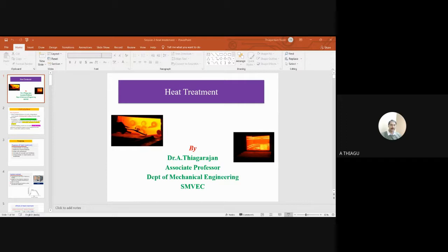So what will happen? The previously strain hardened metals are removed and the ductile property is increased. Okay, so now you can look at the purpose. In process annealing, the heat treatment is often used to soften and increase the ductility of a previously strain hardened metal. Previously strain hardened metal means after completion of the fabrication process, for example casting. Okay, so this is the particular temperature we have to fix for process annealing. So now you can imagine that in process annealing we have to take the low temperature. The percentage of carbon is very limited, 0.25 percent, and I suggested the temperature from 550 to 650.